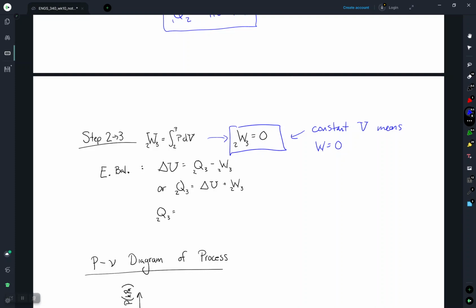So we can solve then for Q. Same basic thing, so we can write the total energy balance here at the top, and then we can rearrange that. We have the same mass. Our delta U is now final minus initial, so it's our final U, 4273, minus 3594 kilojoules per kilogram, plus our work, which is 0 kilojoules.